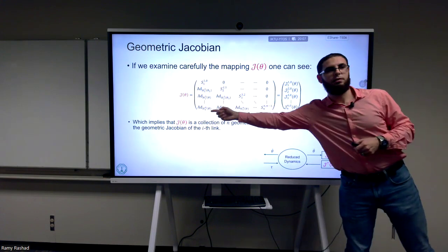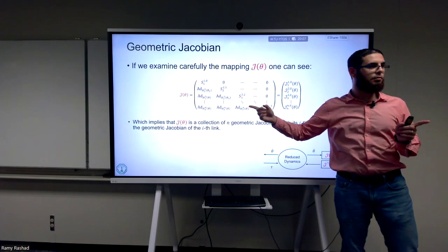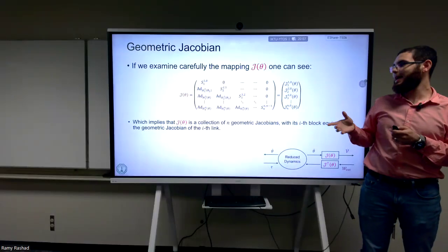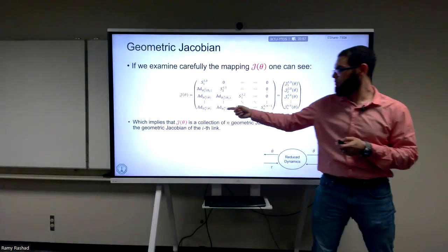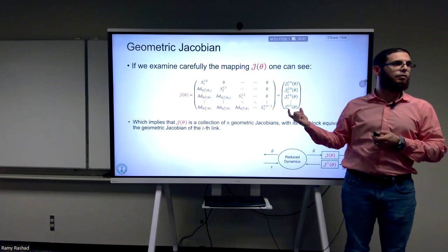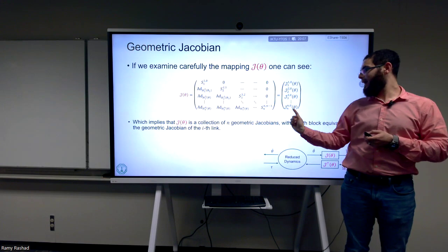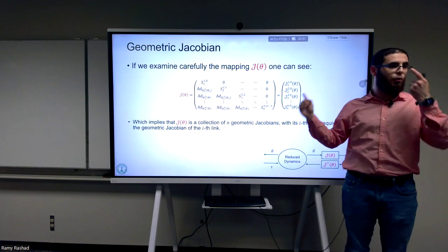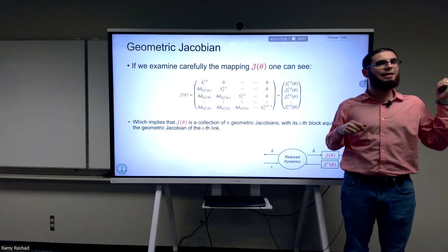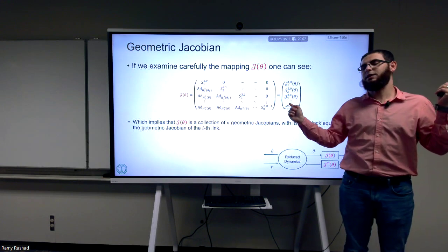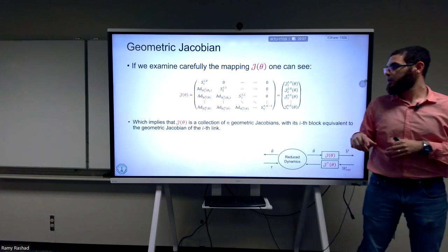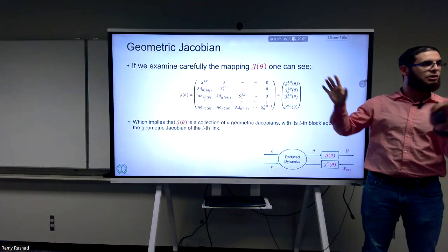This is similar to what? The Jacobian, exactly. We had one whole lecture on the Jacobian. If you go back, you're going to find that this expression is nothing else than the Jacobian of the end effector, the J of n with respect to 0, but expressed in n. In the earlier lectures, we expressed the Jacobian in the 0 frame. And we said that if I multiply this Jacobian by something that transforms from 0 to n, I can have this expression. So these are all just an aside.